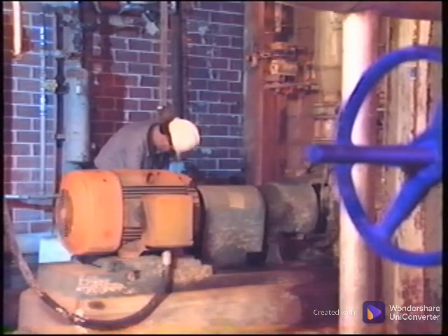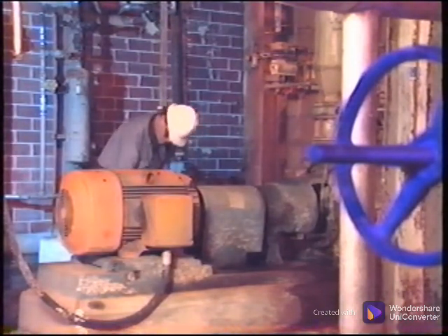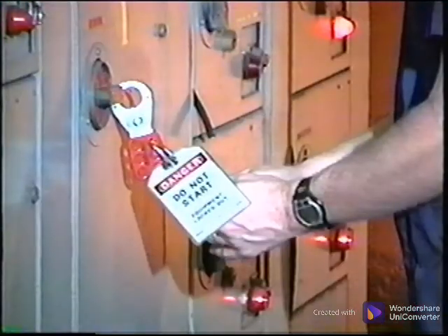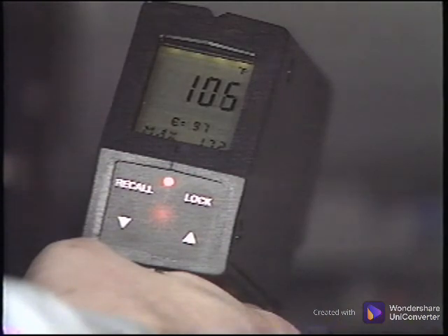Inspect the base plate, foundation, grout, and hold downs. Notify operations and follow all safety procedures to shut down and lock out the machine. The online temperature data will be used later to help you determine thermal growth.